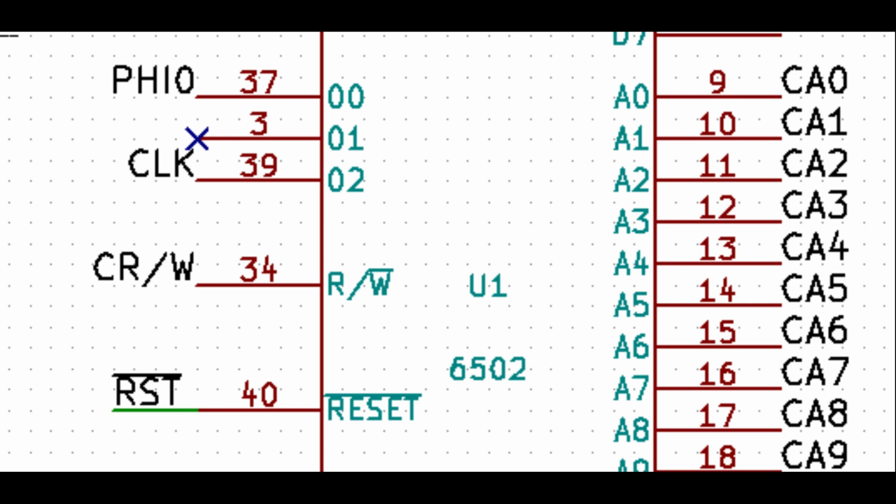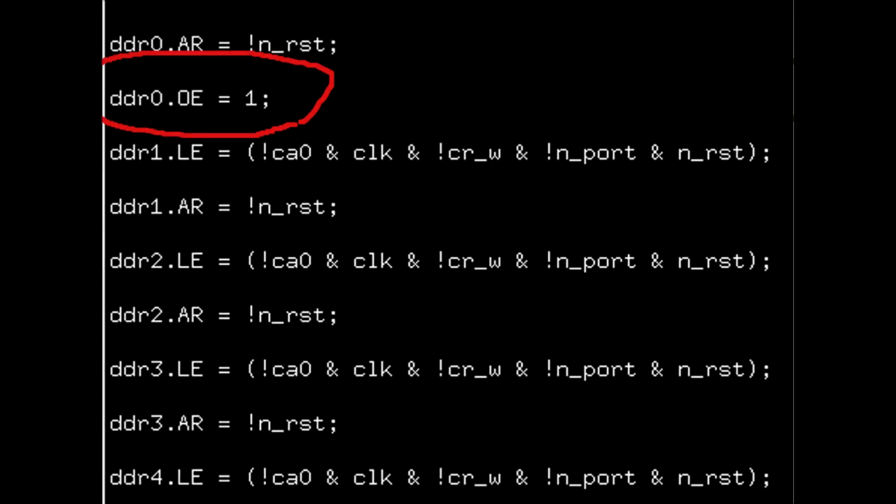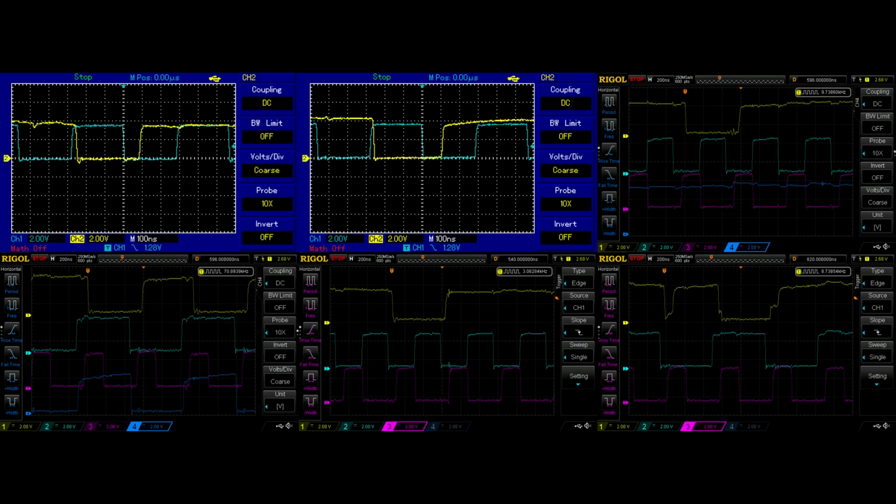And then I found and corrected some mistakes I made in the first logic design, like setting the output enable on an internal node, which not only is not needed, but can cause a random external pin to become an unwanted output. The last design change was about the infamous gate input signal to the 7501 CPU. Not having any such working CPU at home, I had to ask for help on the CBM hackers mailing list. Luckily, a member of the list provided many scope traces of the signals of a working CPU, and that helped me a lot to figure out what the designers intended to do.